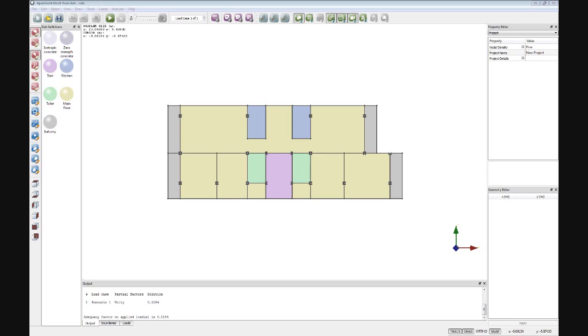Just while I'm waiting for some questions, just a couple of questions that have come up in the past. One question has been, can slab depth be varied linearly across its span or width? The answer is not directly. However, what you can do is prescribe or define a series of zones, each with different properties, in order to have a sort of piecewise representation of a slab that varies linearly. In the future, we may add this functionality.